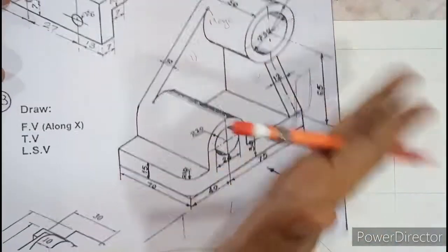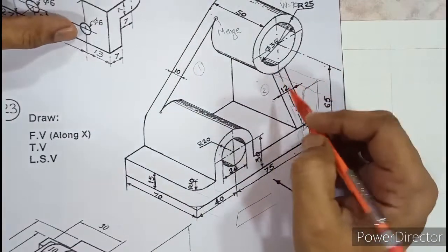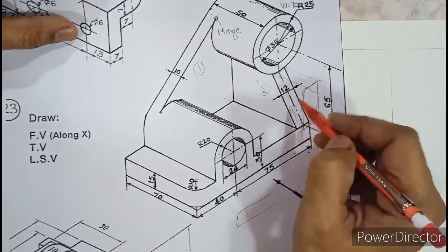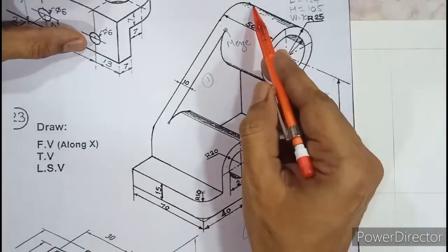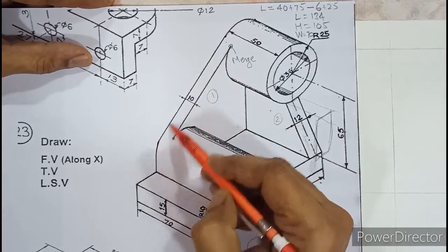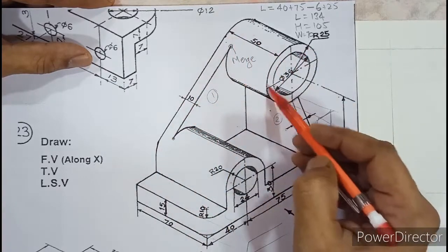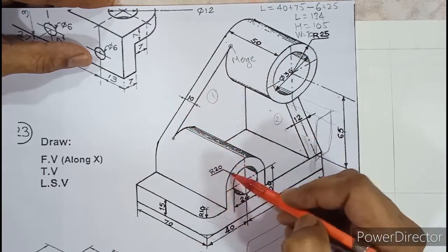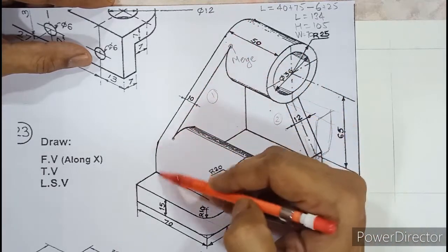Okay, so this is the front view we've drawn till now. Now you can see that there are no hidden lines in the front view, because from the front all the rear edges, for example, look at this rear edge, cannot be seen from the front, but it overlaps with the front edge. It overlaps with some part of the circle, some part of this rib, and then this one. So there is no hidden line for this edge.